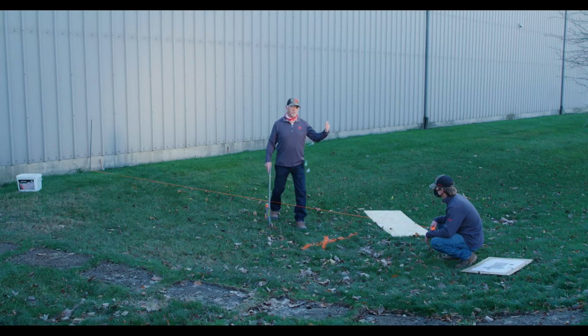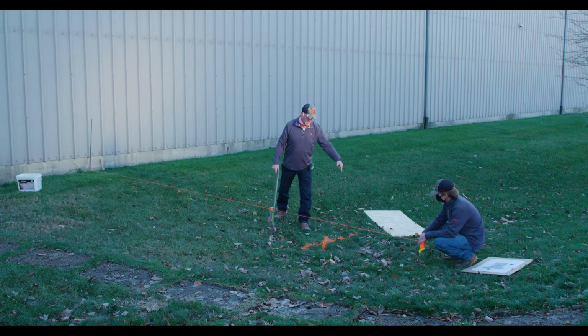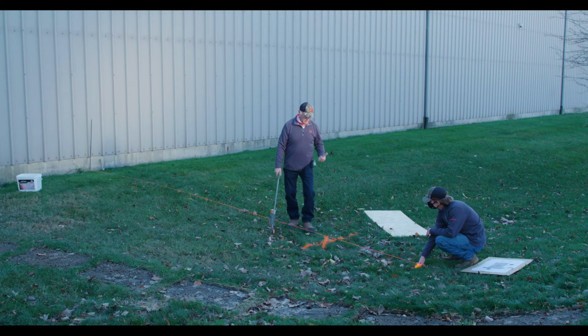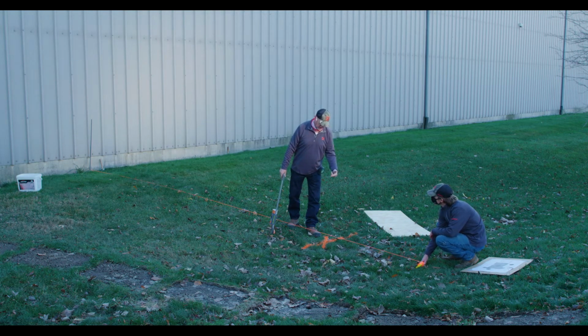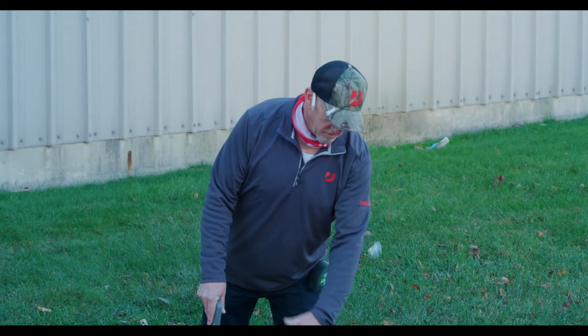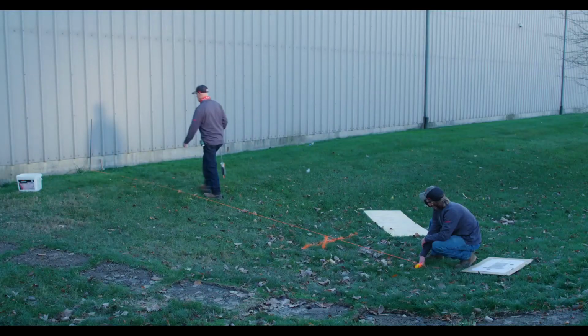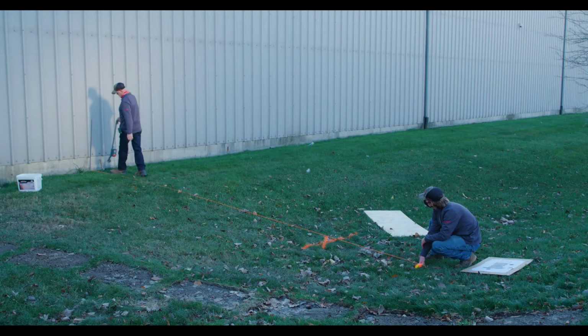Now I'm going to direct Jim to the intersection of these two. You're going to be down, over this way, slightly, back, back. Okay, that's good. So I'm centering that line off the intersection of these two. Stay there, and I'm going to paint this as my perpendicular line.